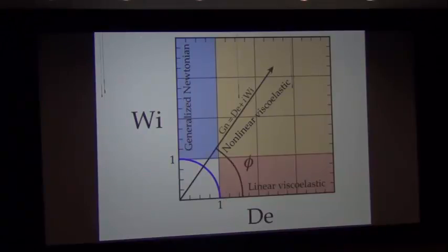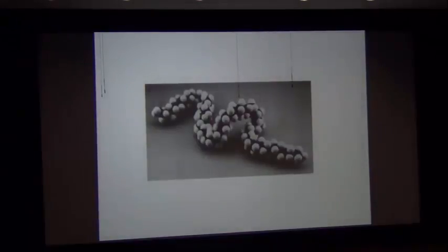On the other hand, we've mentioned the experiment that is used in the chemistry lab for measuring eta prime and eta double prime. That's along here. If you wanted to understand what happens to the fiber after it emerges from the die, when it is shaped and stretched, for instance, then this part might be more relevant. Blow molding, film blowing, these kinds of processes are high Weisenberg number, high Deborah number problems. Now, we're chemical engineers, so you know a molecule doesn't look like a dumbbell.